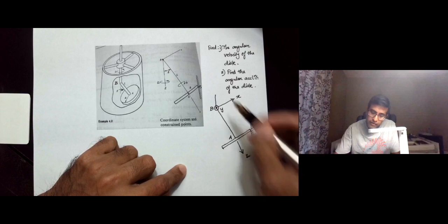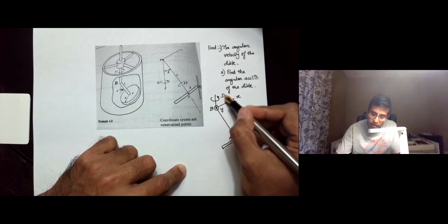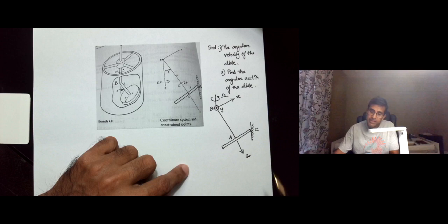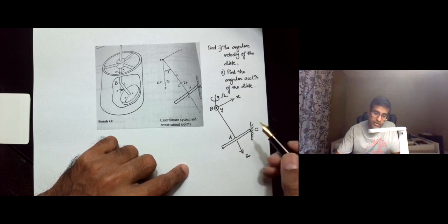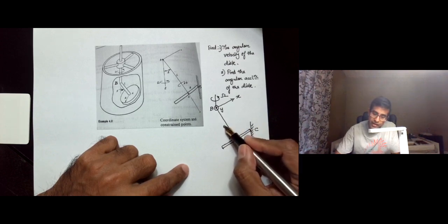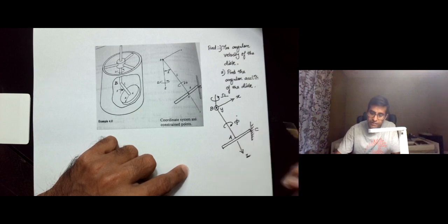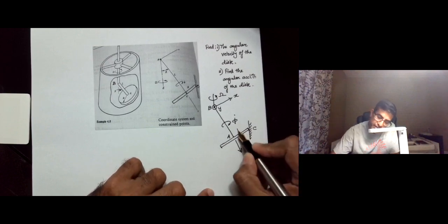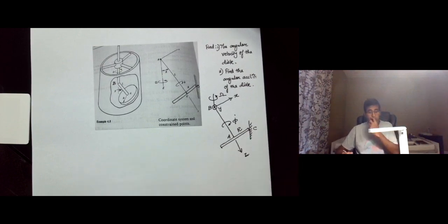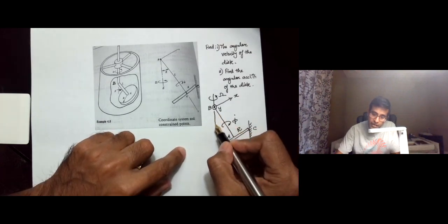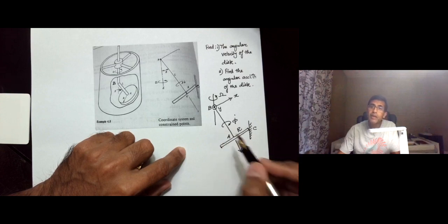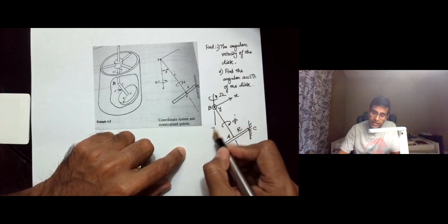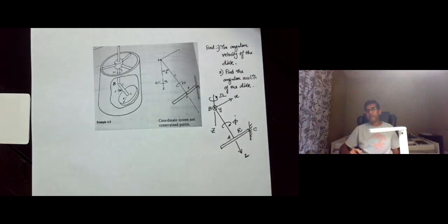Now this bar is turning with an angular velocity capital omega, and as it turns and the disk rolls without slipping, the disk has an angular velocity phi dot. Okay, and this distance is r, the radius of the disk. And by the way, this vertical, which is the fixed vertical direction, let's call that capital Z. All right, so that's the capital Z, that's the inertial z-axis.